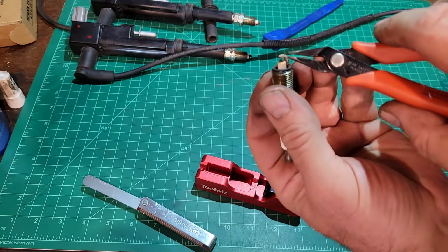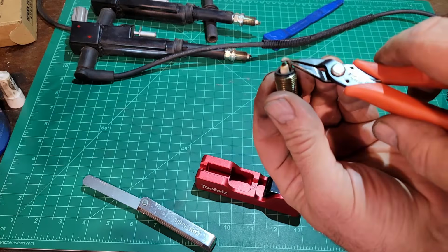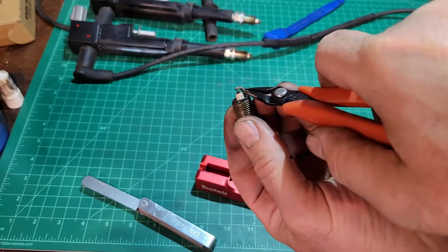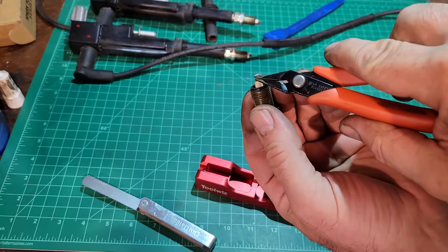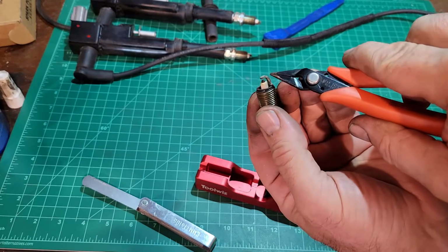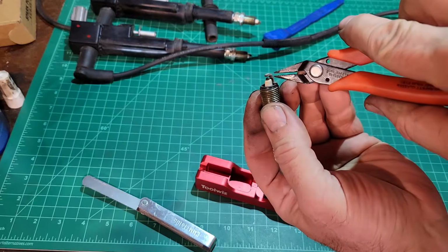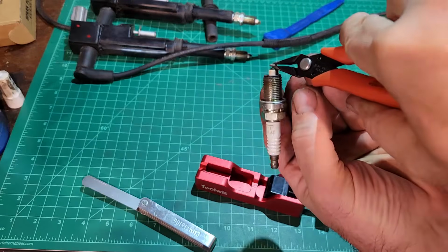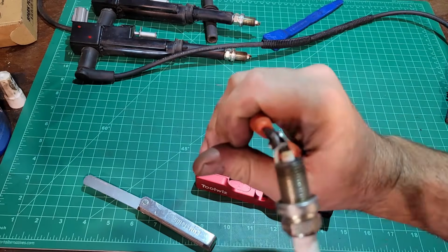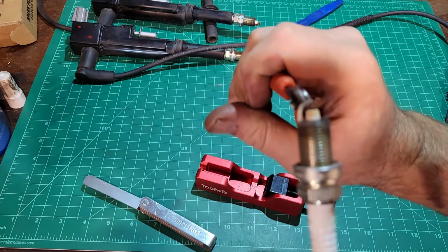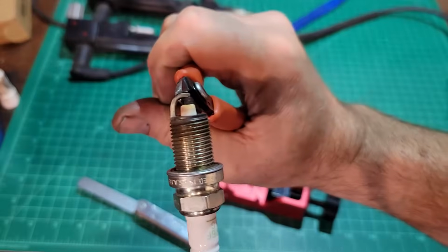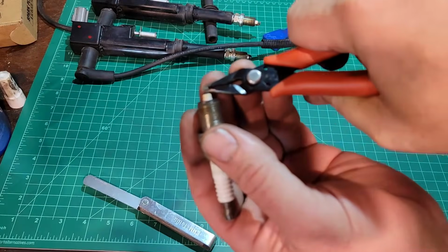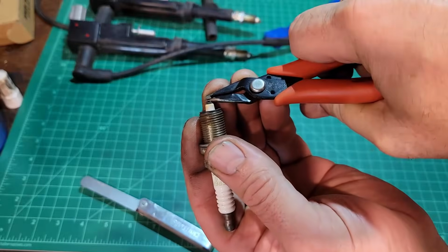And you want to grab these at a point. You don't want to grab them here. I don't know if you could see that. And bend outward, because you're going to move the tip of the ground strap this way. You want to get right here on this bend. Make sure you don't touch the ceramic. See how it's right on that bend without touching anything. And then you just want to give it the slightest of nudges.